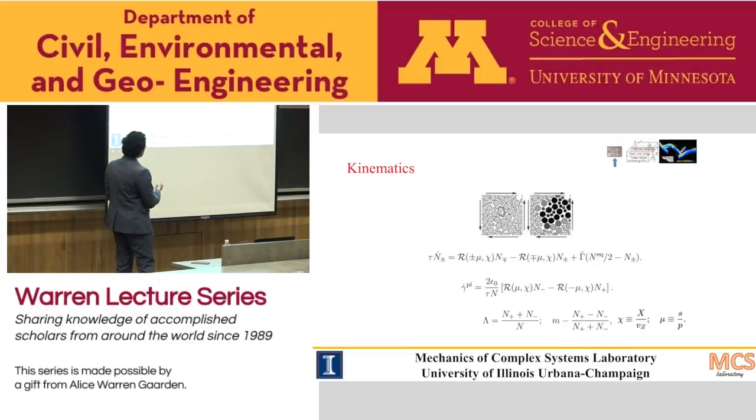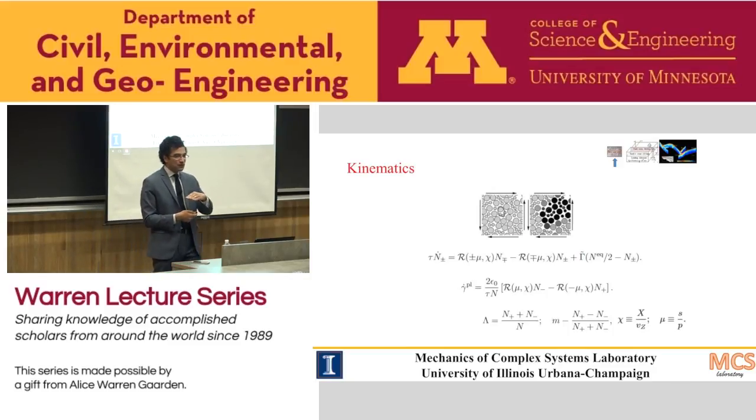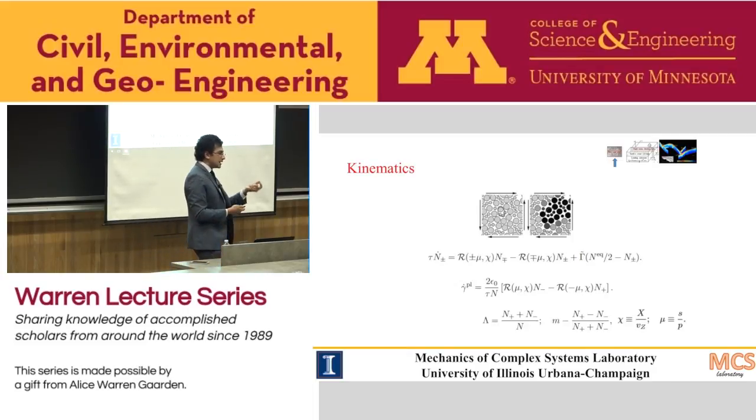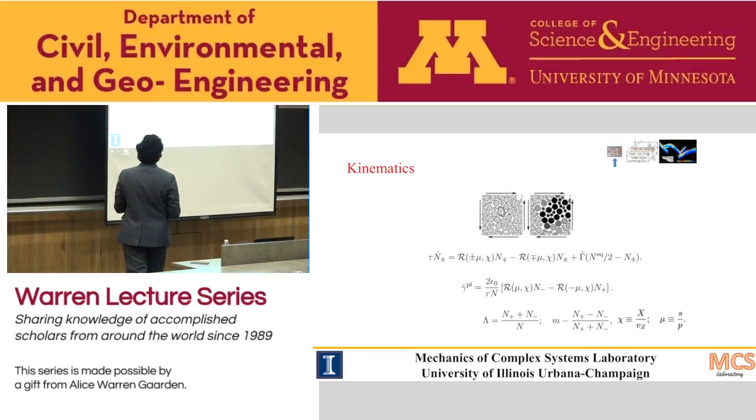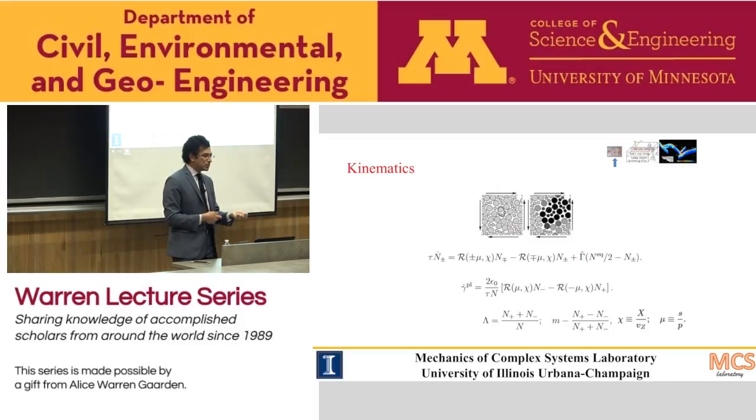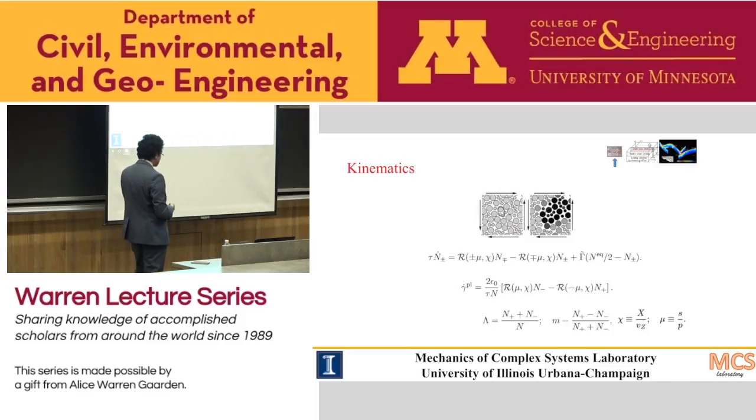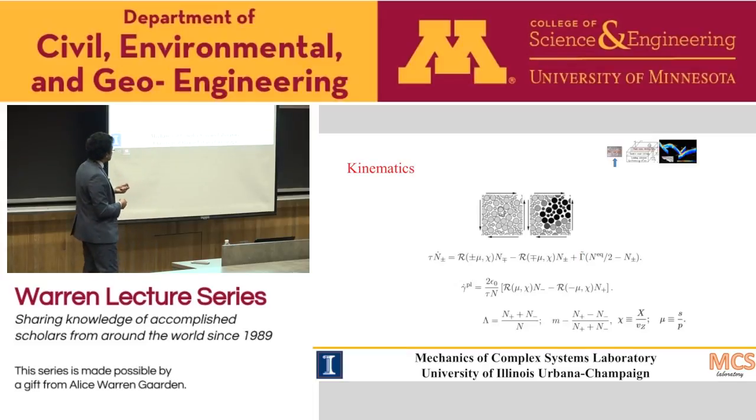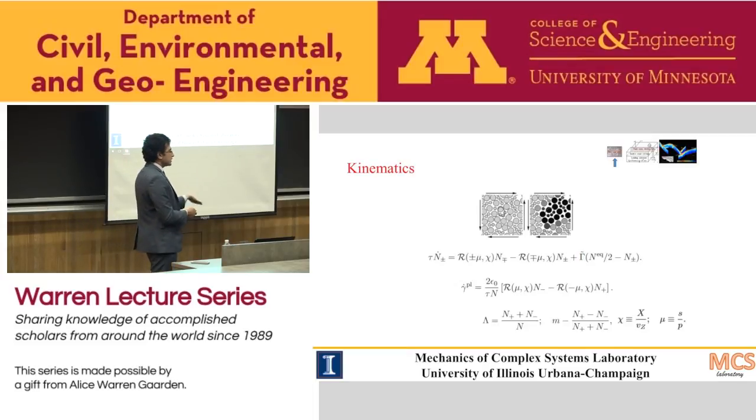If you accept this framework, then we can have a kinematic relation for the plastic strain rate, because with each flip of the STZs, or each local sliding phenomenon, you would produce an increment of the plastic strain rate. And so that would be the rate at which you produce the plastic strain rate. This is a time scale to control this generation rate, and this epsilon naught over n is the magnitude of the plastic strain rate at each increment. So each STZ would produce an incremental plastic strain rate, and this expression will just sum them over all the possible transitions in your material.